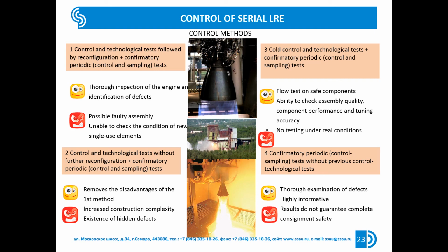Some liquid propellant rocket engines are subjected to a cold process control test without subsequent reassembly. The basis of this test is cold flow tests with simulated propellant, oxidizer and working fluid. The simulated liquids and gases must not react chemically with the structural materials and must be easily removed. The cold process control tests allow us to verify the correct assembly and make sure that there are no foreign bodies in the line of the liquid propellant engine.